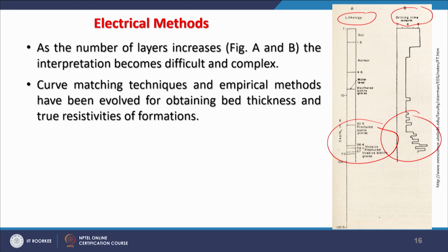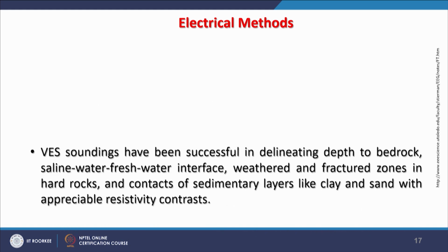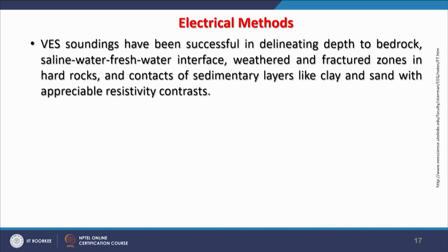Not only that, we are also looking at the thickness of an aquifer or the thickness of a formation, through which we can also find the true densities or true resistivities of formations. So, in case of VES sounding, sounding has been successful in delineating depth to bedrock and the saline water, fresh water interface. In coastal areas or in other areas, if you have this situation, then VES is again very useful.